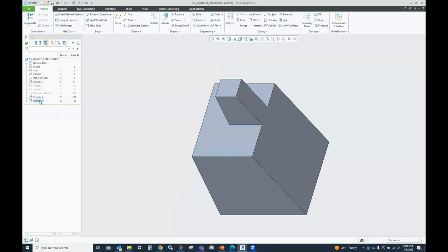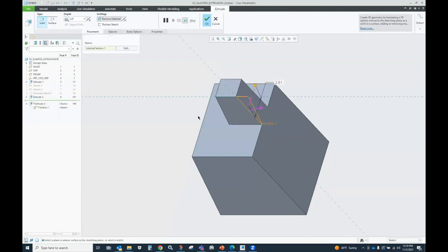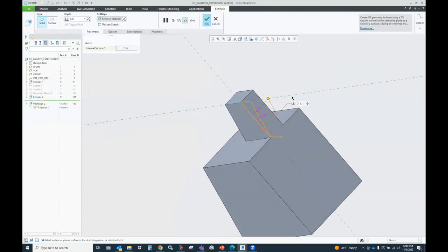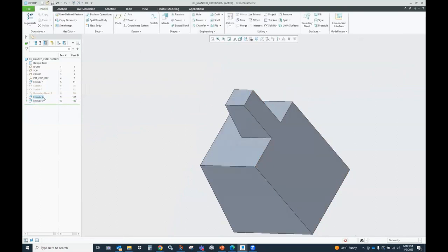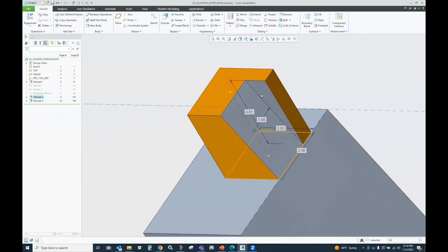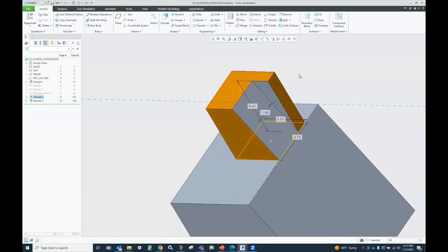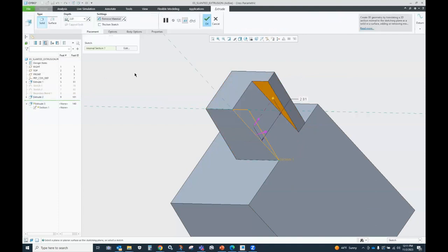First of all, the one thing I did wrong with this was my depth option there. That's bogus, right? It worked here, but what happens if I edit this extrusion and I do something like that? Now my feature doesn't go all the way through, right? So my depth option right off the bat is pretty lazy, if you ask me. I really should use a different option from this list. Does anybody know what the best option is in this case?